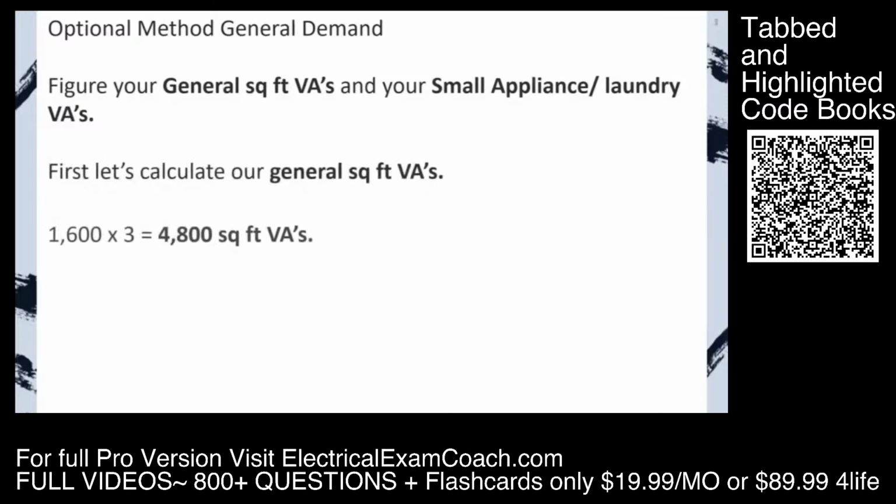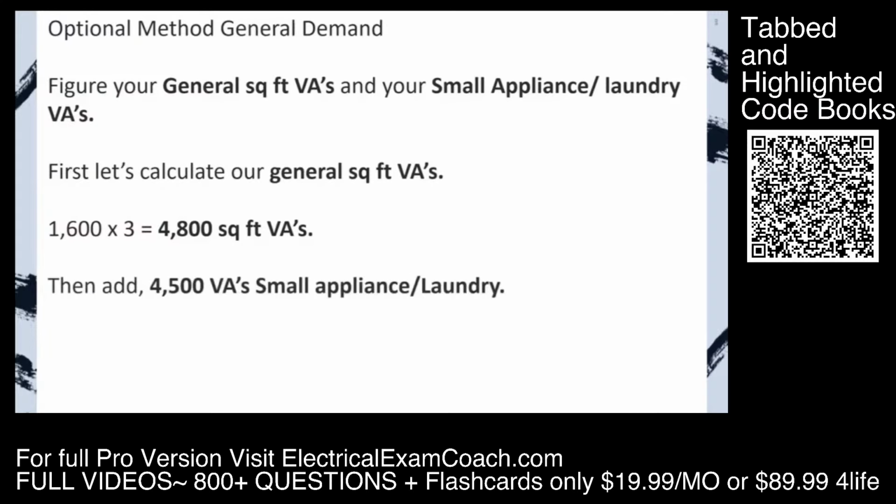We take our square foot. Let's imagine we have a 1,600 square foot house. We multiply that by 3 VAs per square foot. That gives us 4,800. Now we need to tack on our 4,500 for our 2 small appliance and 1 laundry, just like we did before. Now we total them all up. The only difference is that we do not apply any demand factors at this point. We're going to apply a general demand factor later.